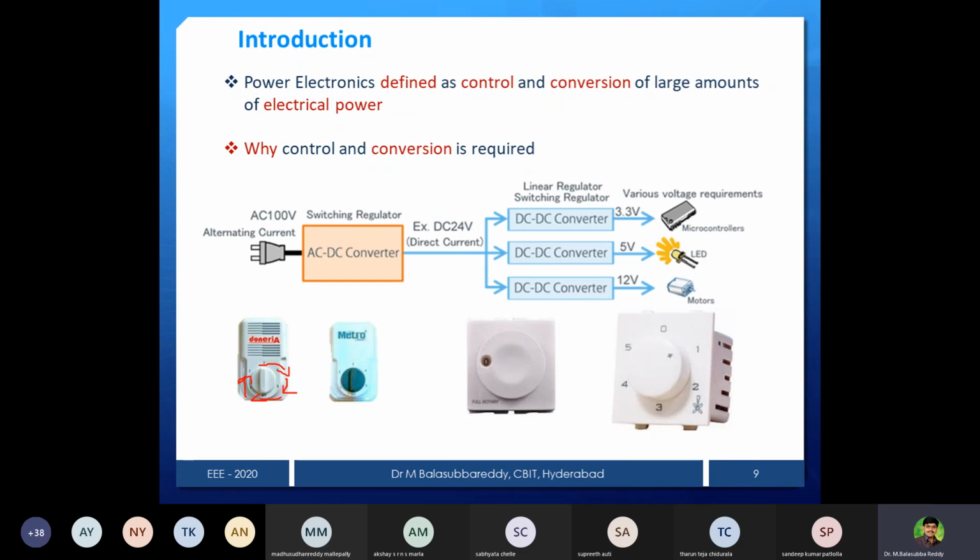Some regulators have smooth variation, and in some regulators they made it in steps. Both are the same, only thing is they take tappings at some points of the angle. Here with smooth variation you can start at 0 and rotate up to 180 degrees. If you keep 180 degrees, we get 0 speed. Initially it is 180 degrees, then as you reduce alpha, the speed increases.